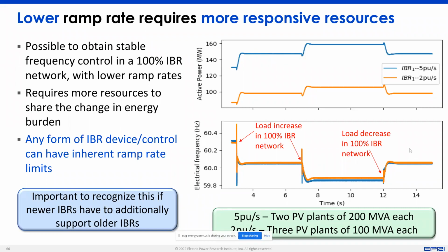Sorry, another hot button. Just quickly on that to elaborate, you can go into it if you accept my earlier rule of thumb, which is amps equals dollars. I'm not giving you the option. Then you can formulate an optimization problem in which you drive the inverter to the maximum amps and pick the angle, the PQ angle, for the best recovery.